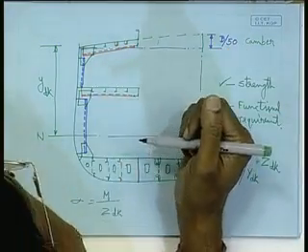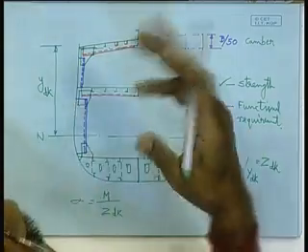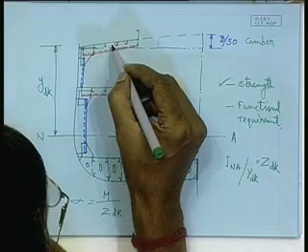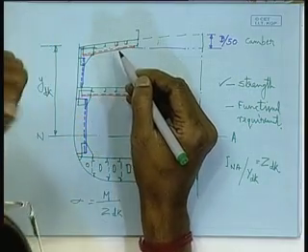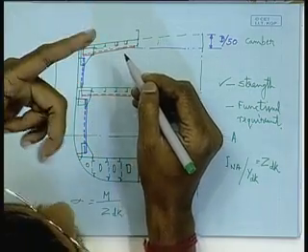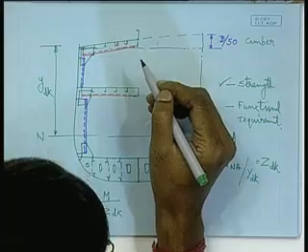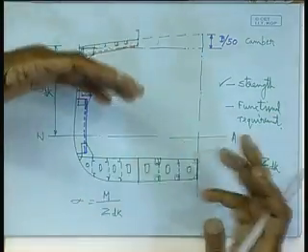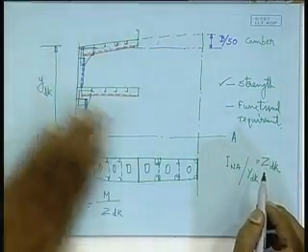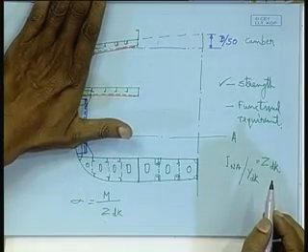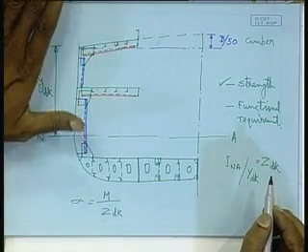Now, which one is to be increased? Those decisions are to be taken. It is better to increase at the deck level, which is furthest away, that provides for more section I value, right, all that. So, one or two or three iterations may go till you get the final scantlings of all the things, right.